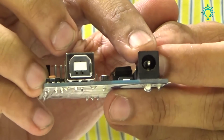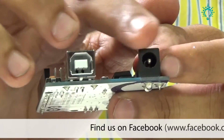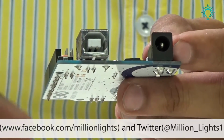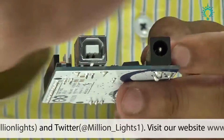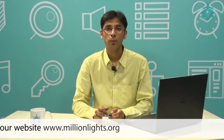The first and foremost important thing is this. It is used for powering the Arduino. As you might be aware, any electronic device requires power for working. You might consider your mobile phones, laptops, PCs, TV, every electronic device requires power for operation. In the same way, Arduino requires power for operation. You can either connect an adapter of 7 to 12 volts to this power pin, then it will work, or you can also connect a battery pack. So you can take a battery and connect it to this port. You can connect it with the help of an adapter or a battery, it is completely fine, but it requires constant power for working.